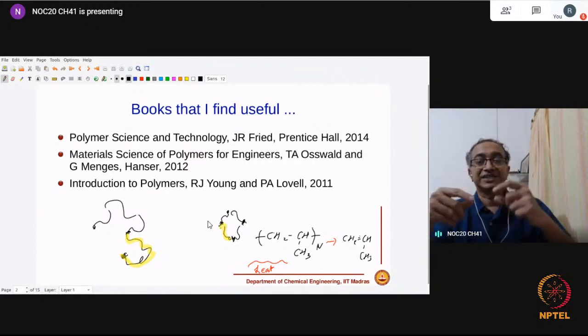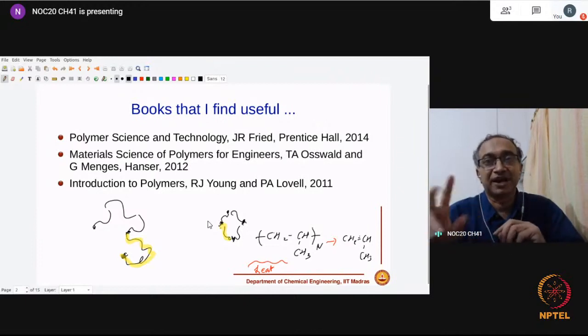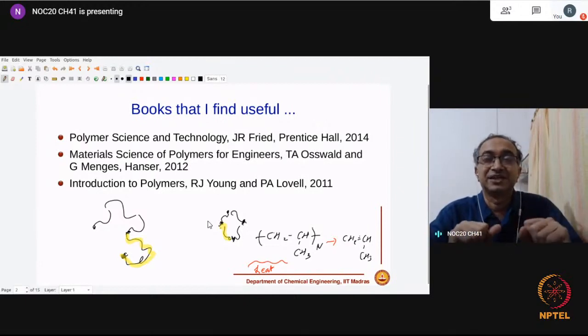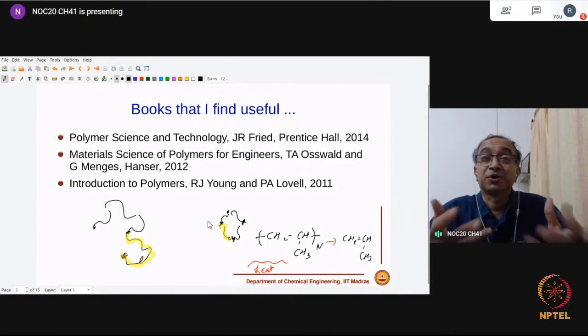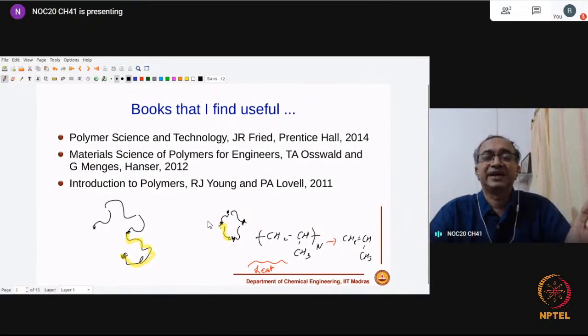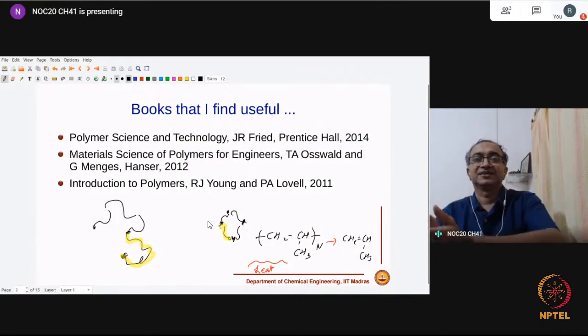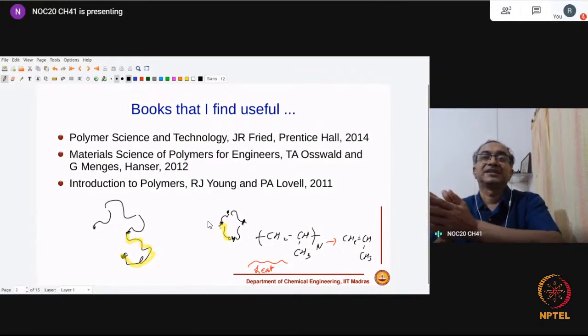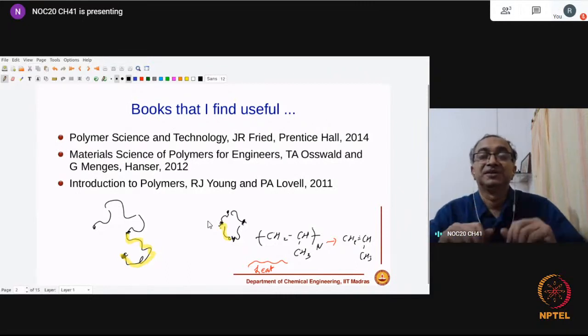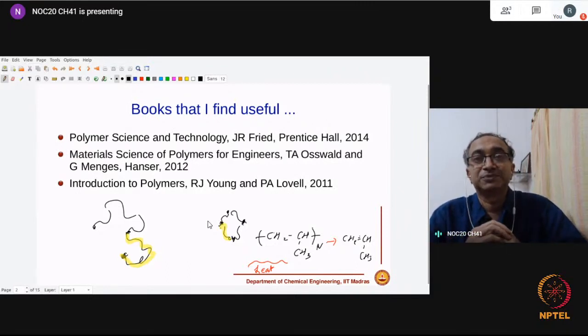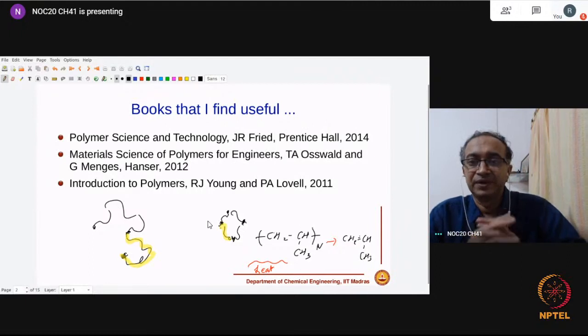But if parts of the chain get oxidized and you get some hydroxyl group or some ether groups and so on, then the properties of that polyethylene will be very different. And if molar mass is not very high, again, properties will be very different. So yes, theoretically, it's possible to get cross-linked polyethylene and get thermoplastic polyethylene, getting a linear and branched polymer. But practically speaking, there are limitations.